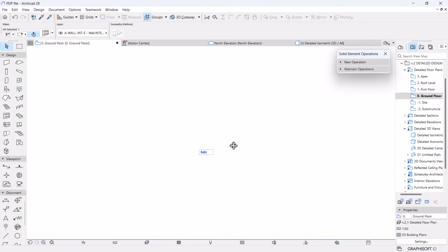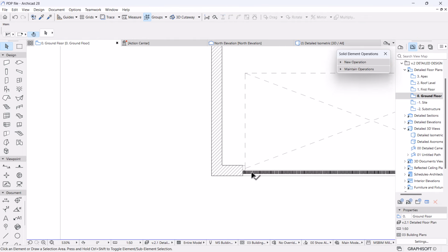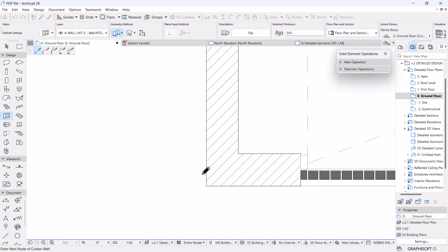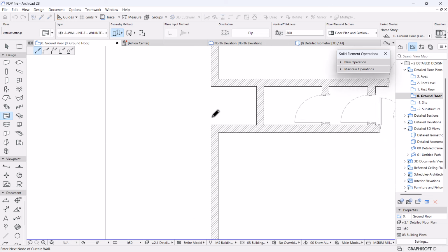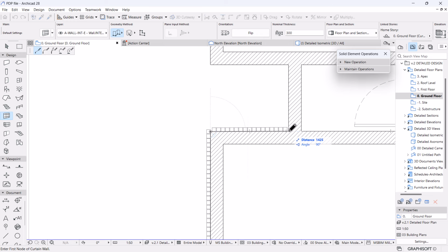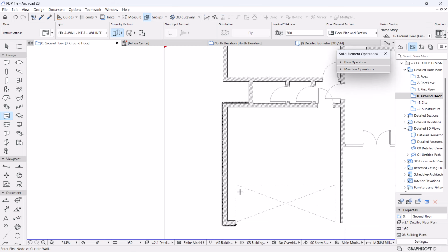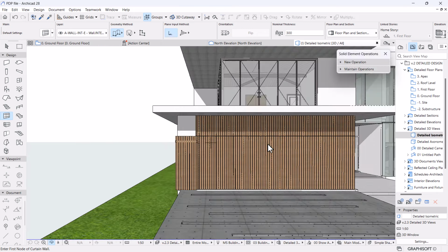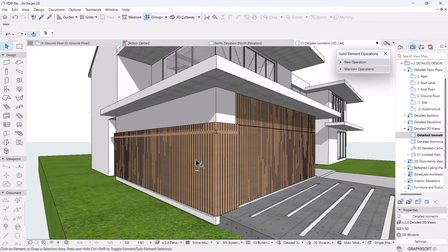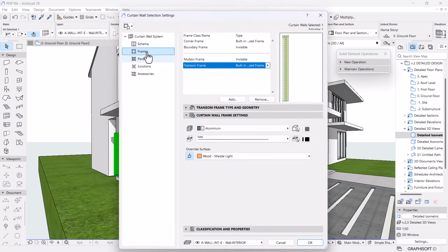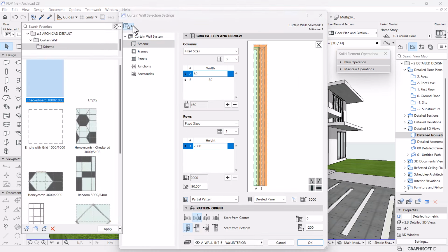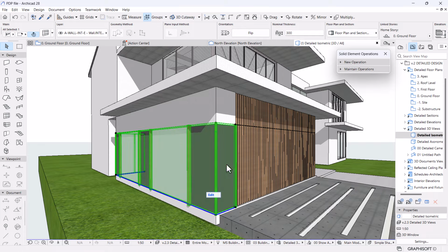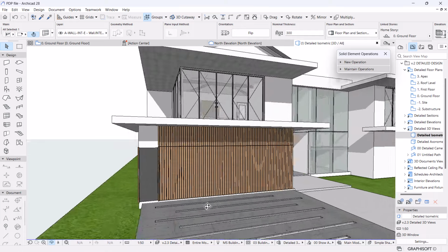So I'm going to come here on the ground, then pick the same material. I'm going to clad it from the right inside going all the way to the outside like that. Even here, there we go, and then right click and hit enter. Even though we're going to have the windows on the side, we're going to punch a hole in our cladding. So this one I'm going to go back to its settings, and let's pick, I think this is the one that we've used. Okay,